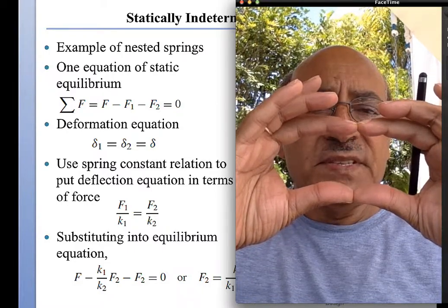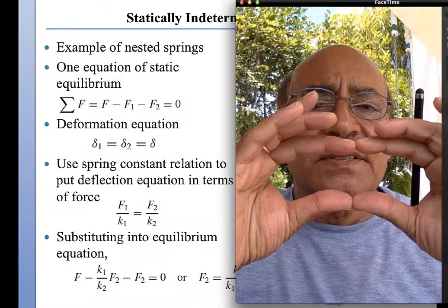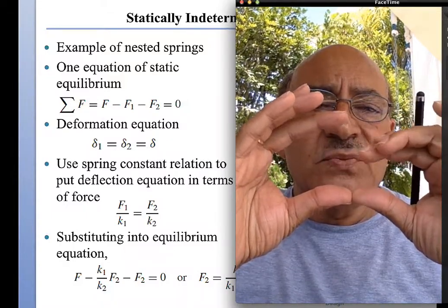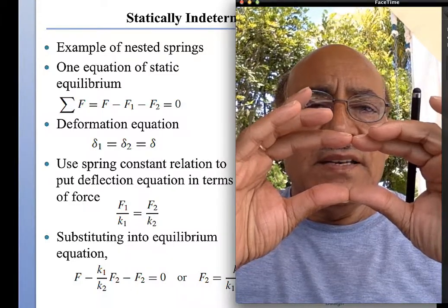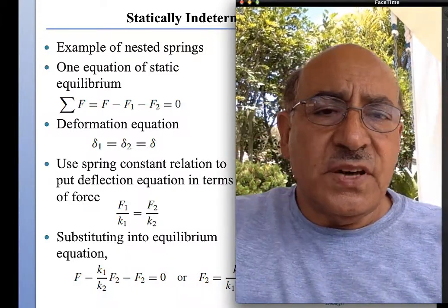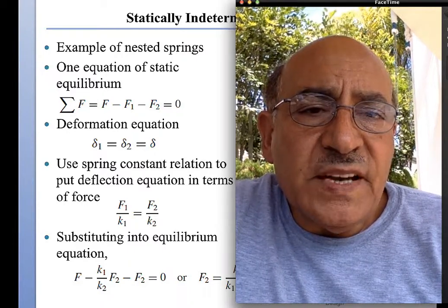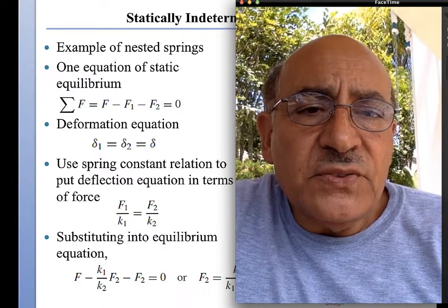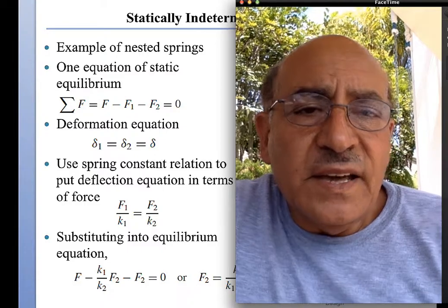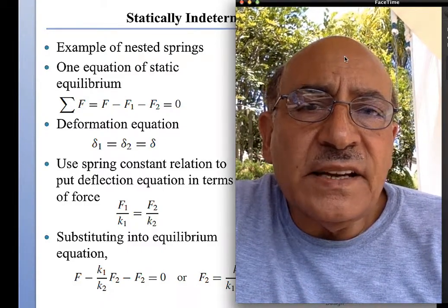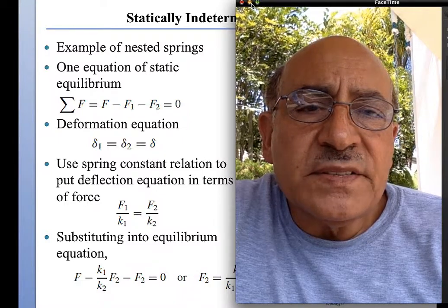So I push from the top, then the force that is applied is going to have to be split between this one and this one. Is it going to be split half and half? No, because the stiff one is going to obviously take up most of the force. Then how do you compute that? And that's the genesis of the idea of statically indeterminate systems.